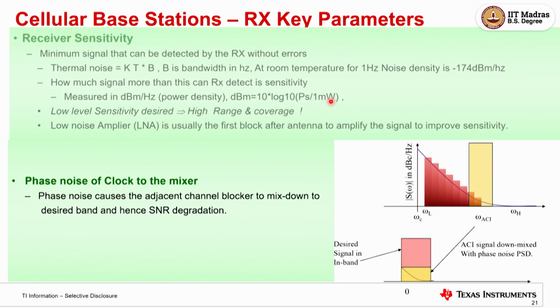And this is also phase noise, as we talked about in TX. A clock is not a single tone, it has a spread. What happens is when you multiply with something which has a non-ideal skirt, we said any multiplication just adds and subtracts frequency. So if something is residing in your nearby band, like the green interference in the previous one, it will take some part of that information and put it in. There's a residual information, so the phase noise should be very good. Otherwise it folds and gives back that information. So that is also a problem.